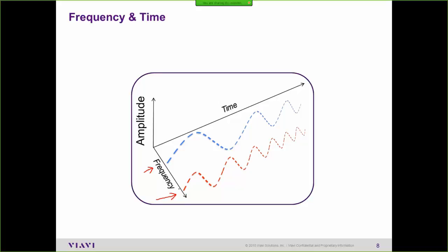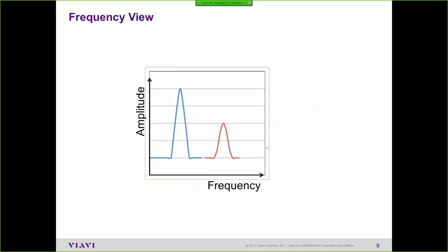And actually, you'd see the composite, which would be the black signal. So the red and the blue add up as they go positive, and then when the red goes negative before the blue goes negative, it draws down the composite signal. And so you get an idea here of what the signal looks like as a composite. So that signal, the black line on the screen, is made up of two separate signals at two different frequencies.